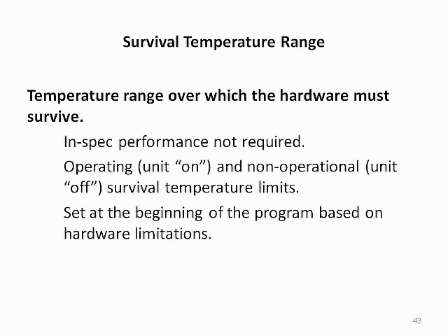Spaceflight hardware is often, but not always, tested to a wider temperature range over which the hardware must survive, but where full specified functional performance is not required. Such survival temperature limits may be established for cases where the unit is either on or off and are typically defined at the beginning of the program based on hardware design limitations.